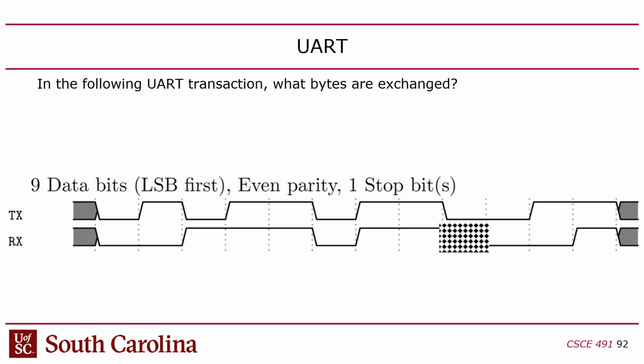Now the problem is, I'm actually not sure if any UART hardware has the ability to know a bit is wrong. It's possible because, if the flip-flop that's receiving this goes into metastability, I think there is a way to detect that potentially. If you have a timing error because the phases don't work out, I think there is a way, but I don't know how common this is. But for the sake of argument, if I knew that was an error, you can actually fill it in.